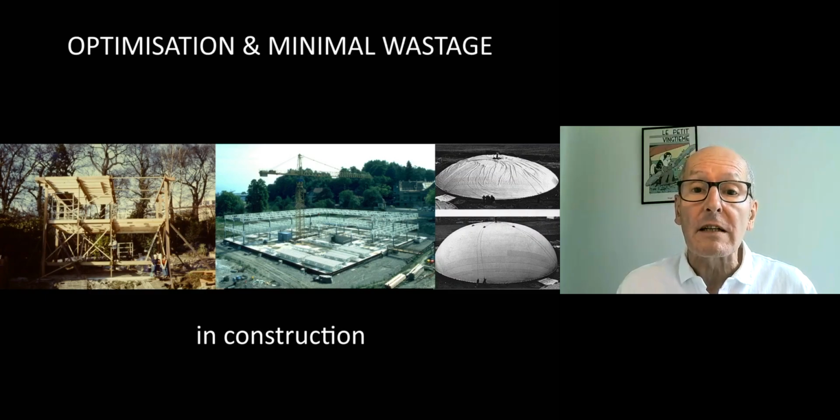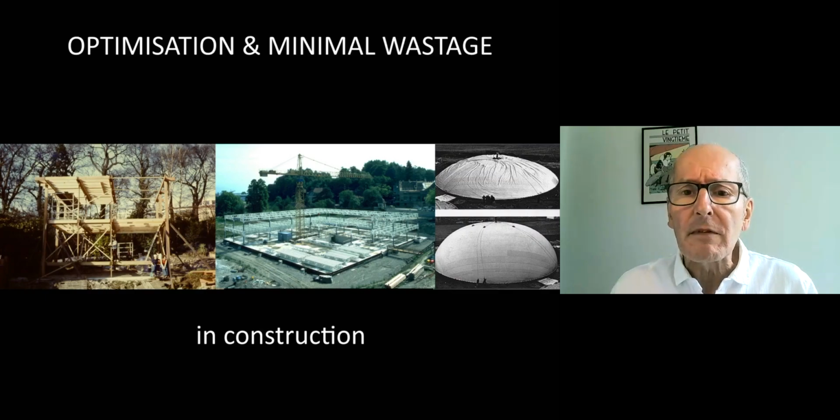and making assembly, on-site assembly, efficient and fast. And the third one is these extraordinary domes designed by Dante Bini. Bini shells, they were called. Dante Bini invented a new way of casting concrete by inflating them using pneumatics, rather than building huge timber formwork. He basically inflated the concrete dome. So that, again, is an incredibly efficient way of looking at putting structures together.